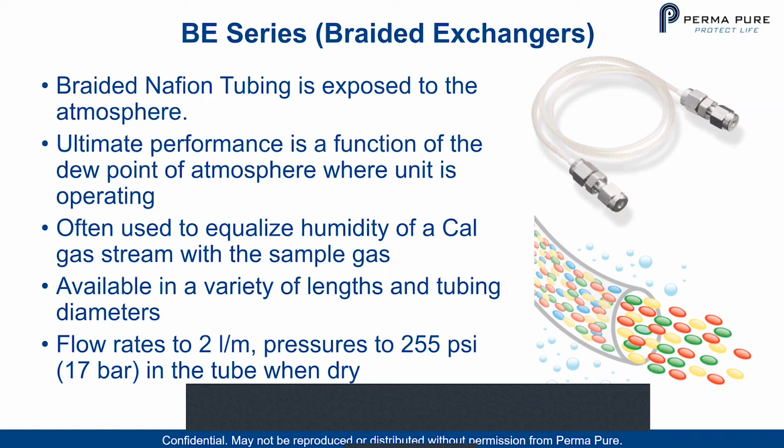We can attach a metal connector, a typical compression style connector, and we have a very strong strain relief. That means we can pull that connector, and the mechanical strength is from the encapsulation or the enveloping of that polypropylene around the netting that has been weaved around the tube.